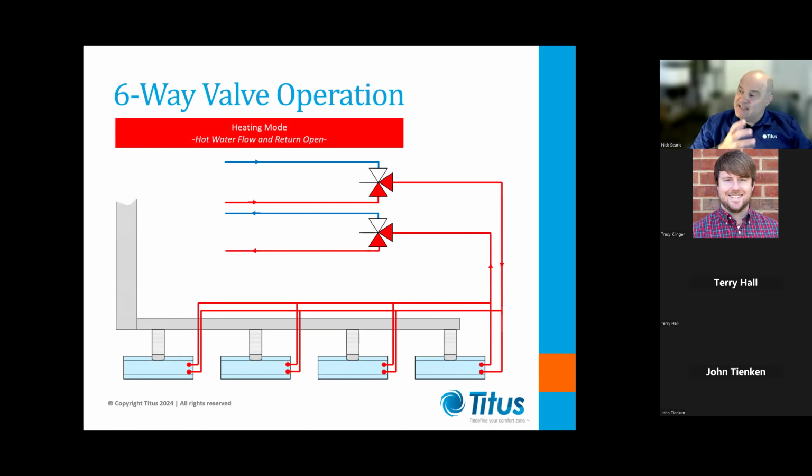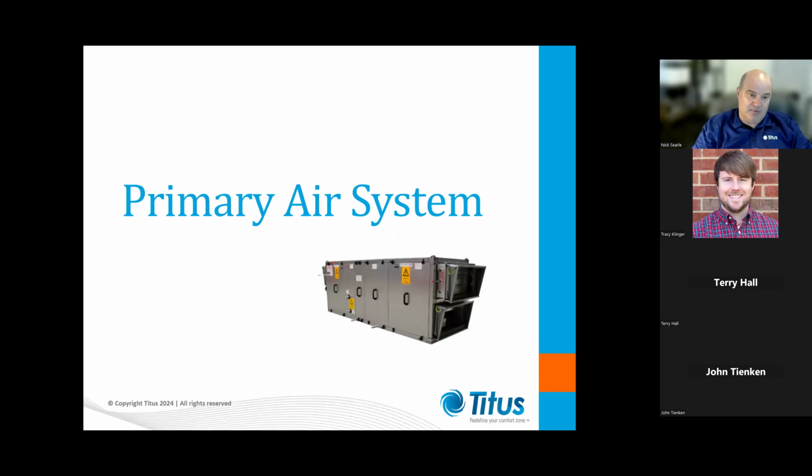So if you're using separate treatments in the chilled water versus the hot water, you cannot use 6-way valves for this application. You'd need to go back to the duct-mounted heater or even 4-pipe chill beams. So that's the downside of a 6-way valve. But they do save even more cost compared to doing the duct-mounted heater, because you've only got one single actuator controlling both the heating and the cooling, and reduced pipe work. So it does save system cost.